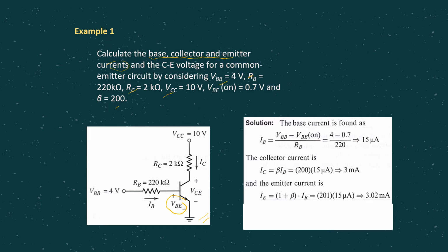Okay, so what you can do is complete the circuit, so it will be easy for you to do the KVL equation. So if we complete the circuit, this particular node is actually connected to 4 volt, positive 4, while obviously the negative one is grounded. Okay, so as you know, ground and ground are the same level, so from here you can actually see the closed loop and do KVL accordingly.